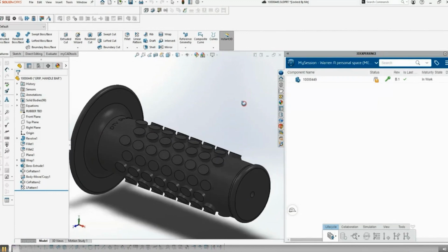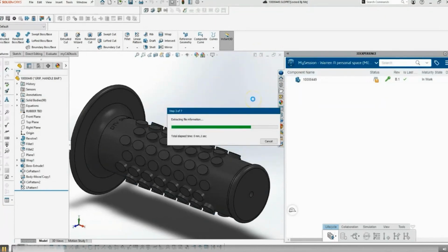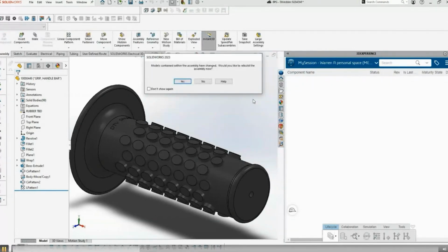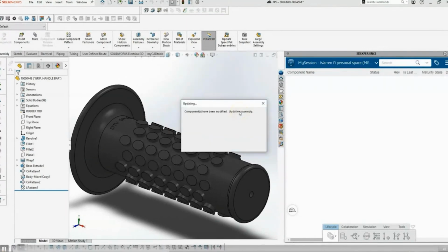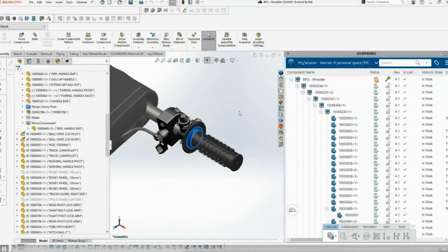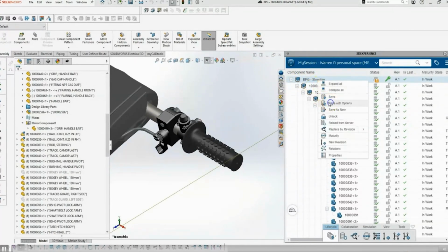So once the file has been modified, we can simply close, right, and save the changes. SOLIDWORKS will notice there's a change made to the file and ask you if you want to save it or not. And it'll also ask you if you want to rebuild the model, because the model has been changed and it needs to now be updated and rebuilt. So I'm saying yes over here inside of the main top level assembly. This component was actually used as a mirror on the left component, right? So all that's left now is to upload to the cloud.